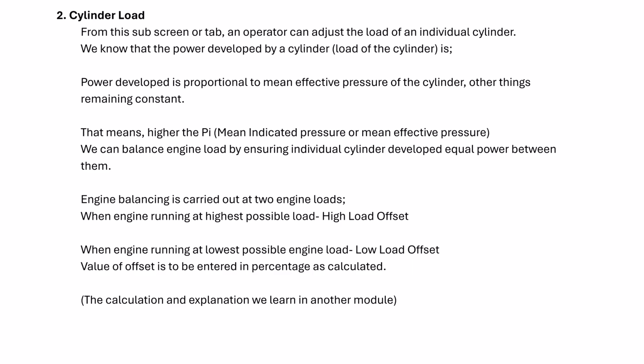Cylinder load. From this screen, from this subscreen or tab, an operator can adjust the load of an individual cylinder. We know the power delivered by a cylinder. What is the power delivered by the cylinder? Power delivered is proportional to the mean effective pressure of the cylinder, other things remaining constant. Correct?